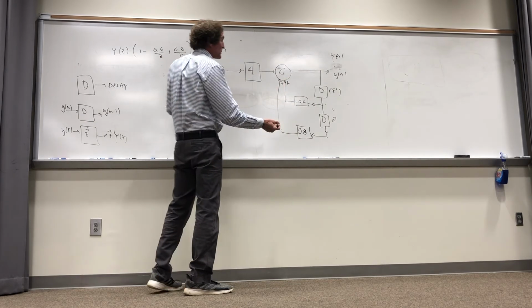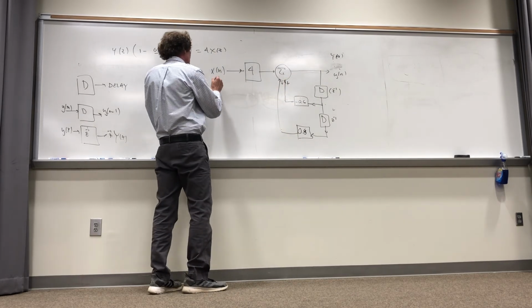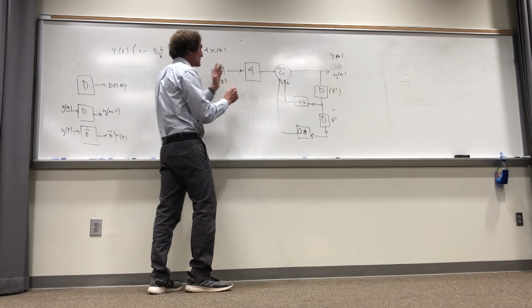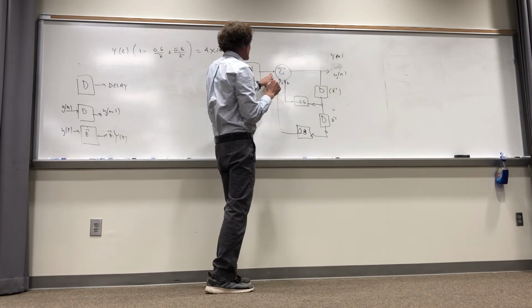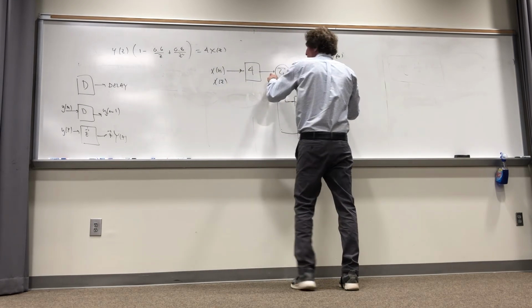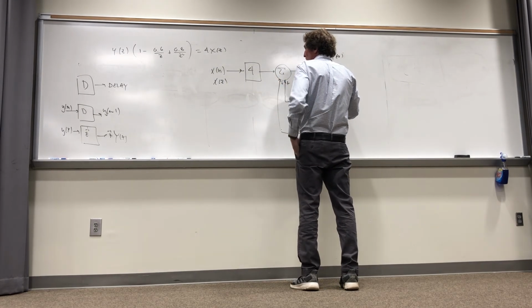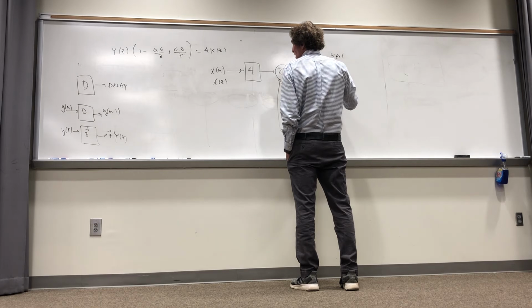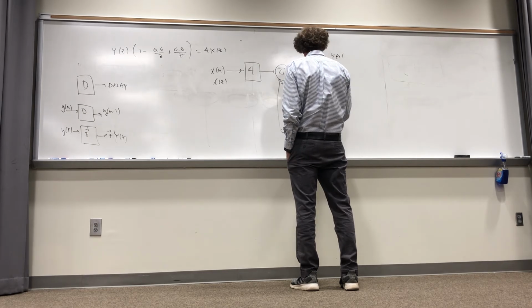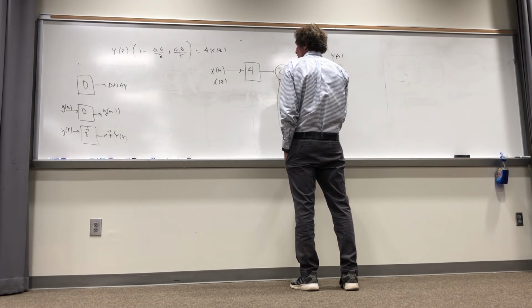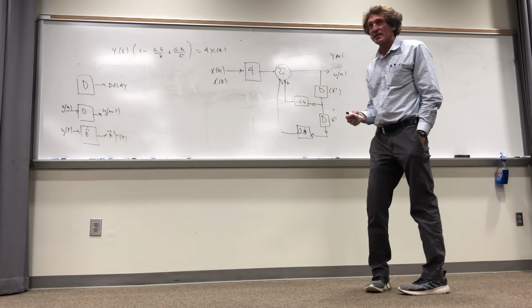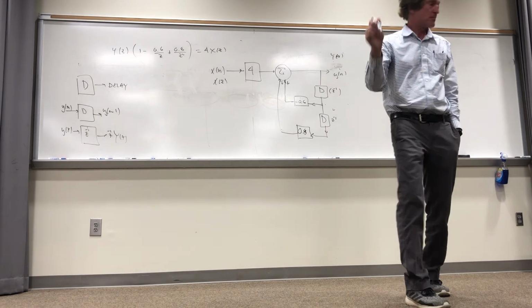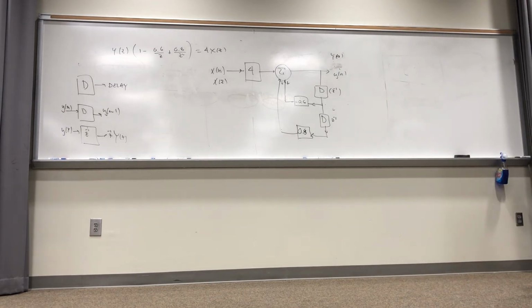And if you look at this, if you're in the z domain, then this becomes x of z, right? Times 4, 4x of z, right? That's going to the output right there. And add to that, the output is going to be the minus 0.6 and the minus 0.8 by 2 delay operators, and that should do it. And that is in your textbook. I'll tell you the page this is showing on.